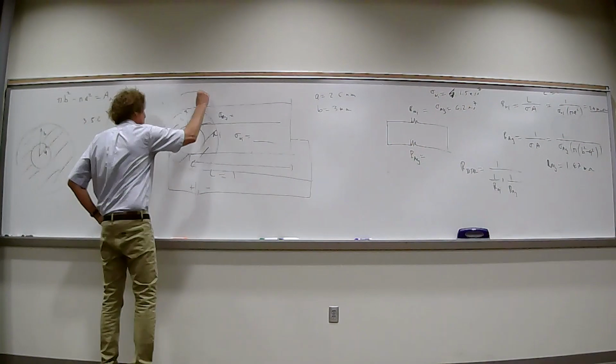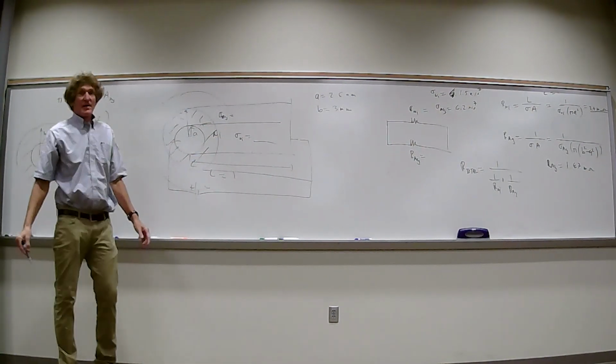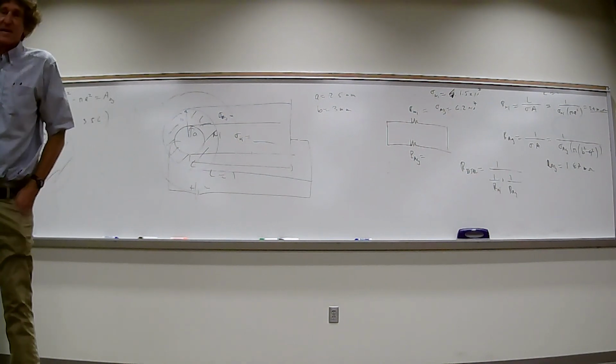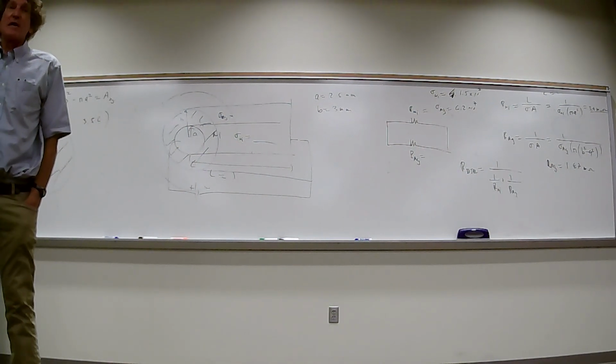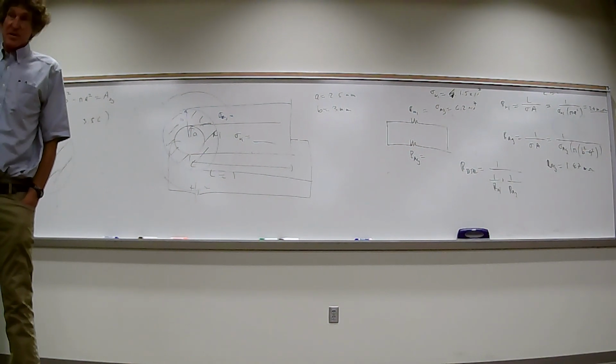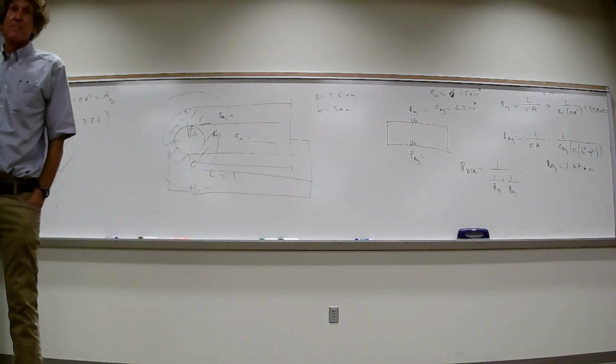What if I put another sheet on? Make that gold. Still in parallel. That's right. How dare you? It's a logical extension, right? Now you get the area between B and C, right? Use that and you find the conductivity of gold, and it's just 1 over the conductivity of gold times pi quantity C squared minus B squared, and then you got 3 in parallel.